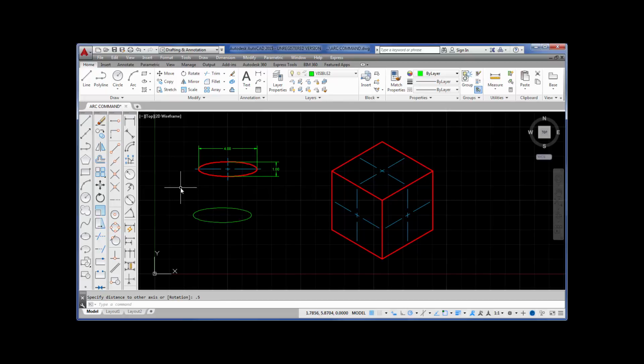There is another way to do this. If you click this down and pick center and pick on the screen, now you are measuring from the center. So for the maximum diameter, you enter half of it, 2 inches. And for the minimum diameter, once again, half, 0.5.